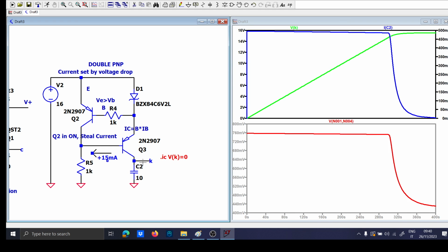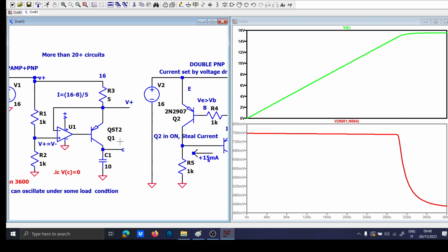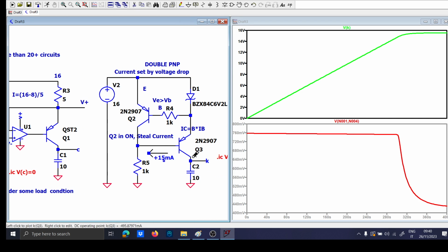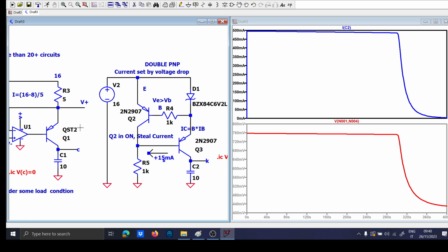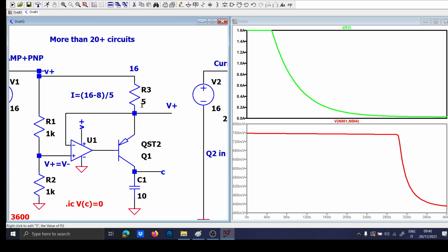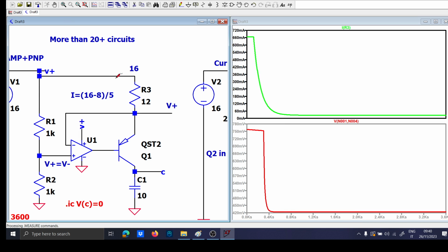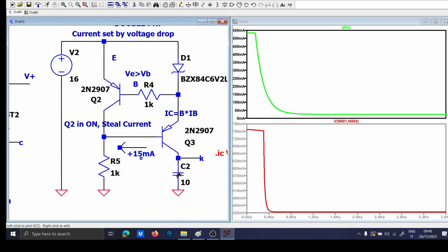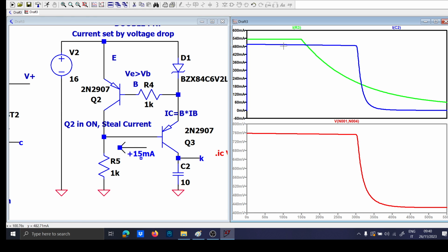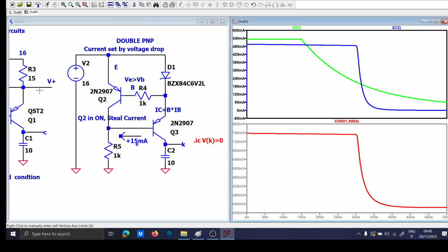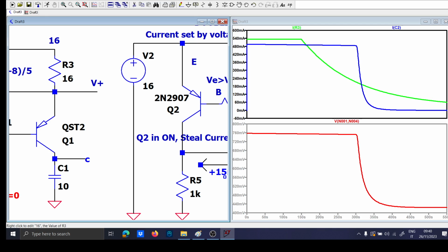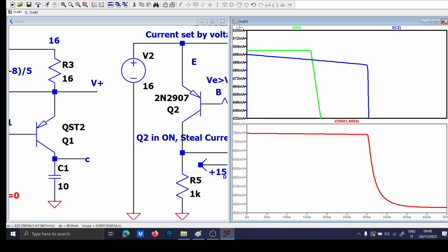The problem of this circuit here: now in this circuit, we have removed the op-amp, and we have still the current limitation to 50 milliamps, which I can do also in this way by putting 10 ohm here. Let's raise it a bit until we have 50 milliamps. Now you start to see the difference. This is more stable. Let me use 60. Okay, now you see the difference.